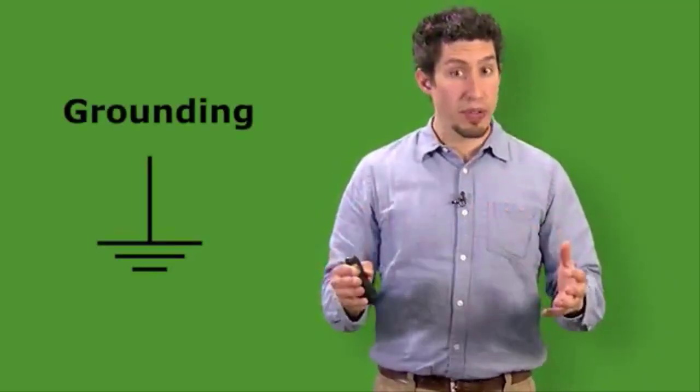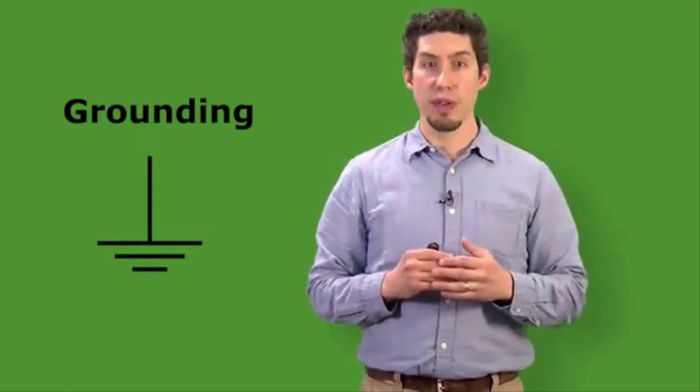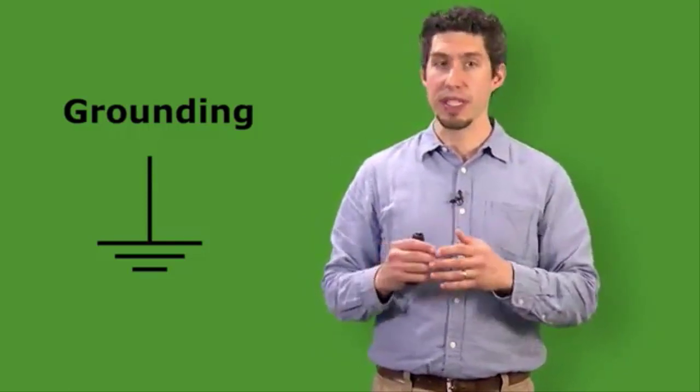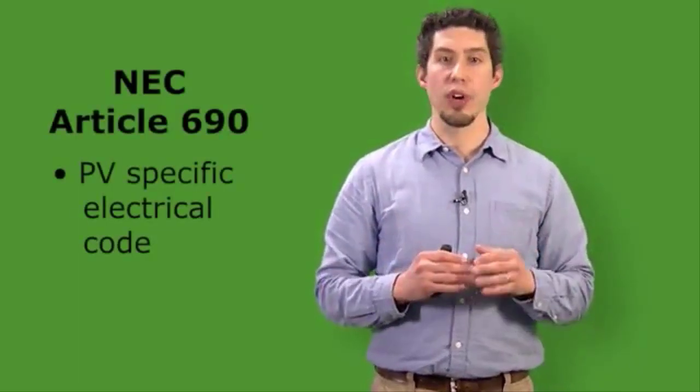There are strict grounding requirements stating that electrical systems are grounded, as well as the metal components of the photovoltaic system and the mounting system. All of these rules are defined in Article 690 of the National Electric Code, which specifically addresses solar installation considerations.